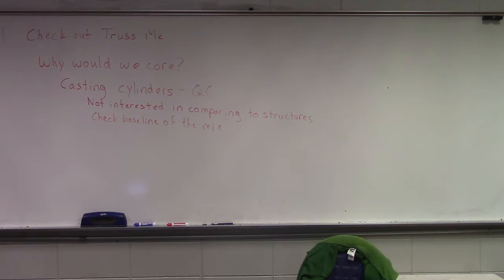So is that stuff, like the retarder you spray on after you finish it, that white stuff, isn't that what that is? No, not a curing compound. So Rush is asking about curing compound. It's a chemical that you apply to the top of the surface. It has a certain amount of particles suspended in water. It sets in on the top surface, closes all the pores, and then the water it's suspended in evaporates. So it blocks all that pore structure, so further water can't get out. We have to be careful with curing compounds to wait and put it on after the bleed water goes, right? Because if we block in that bleed water, all that happens is we're going to strip away that top layer of mortar.